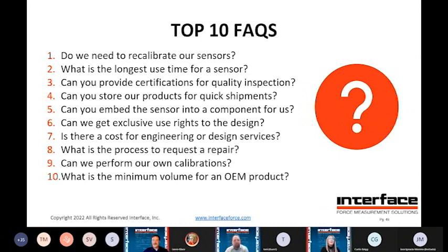All right, Randy. Well, recalibration is going to be up to the application a bit, and also customer requirements. From an OEM standpoint, it really becomes more often a matter of doing good characterization work on the front end to understand the expected life of the sensor, but then also maybe incorporating an in situ check from an operation of the machine. How consistent is it working? How is that sensor working in the machine over time? So periodically, customers will want to integrate additional sensing capabilities to do an in situ cal. So it's case by case, but we can certainly arm tools for that.